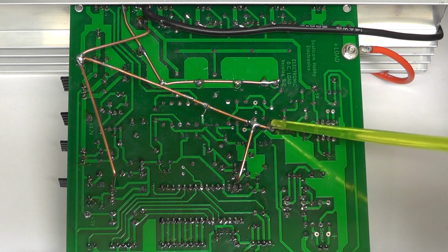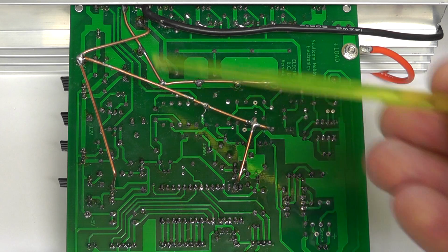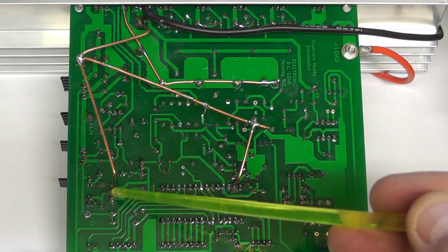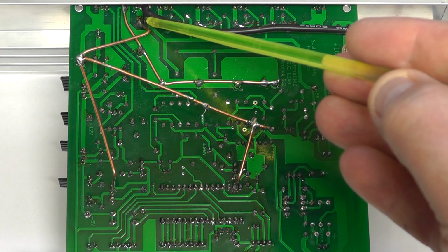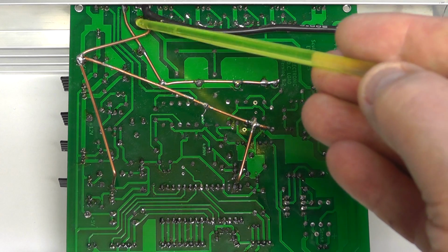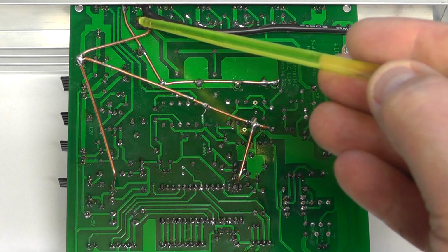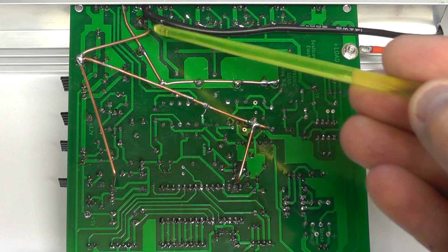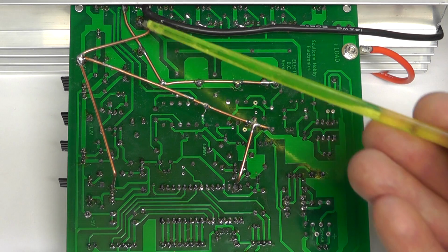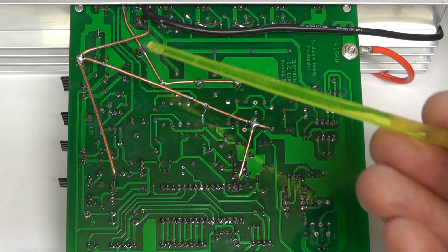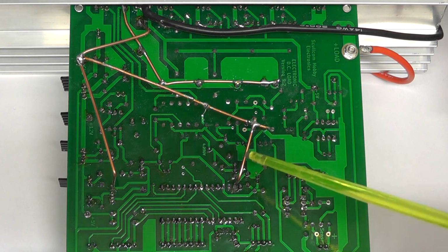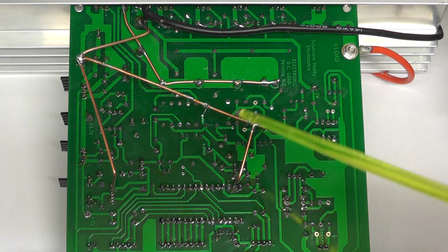6 locations. So it goes there, there, that point there, which is the main ground pin on the test pin, that point there, and then the last point is just there, which is actually the earth return path for the 0.1 ohm sense resistor, which is mounted onto the heatsink. So you need to be careful of that one, and we had to bend the copper wire back at an angle going towards the board, but again away from the PCB, just so it's not touching the heatsink. So that gives us the additional earthing, which certainly improves things and improves the overall performance of the DC load.